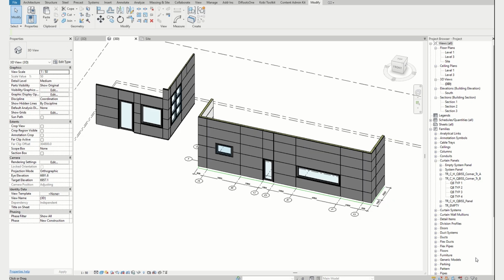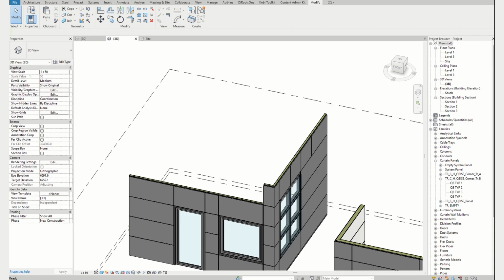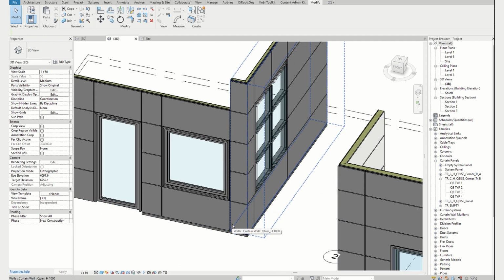We talked a bit about inserting doors and windows. What about the finishing details at the top and bottom? Our main focus were panels and corner elements, but of course we need to define fixing, flashings and ceiling material in order to build facade properly. All these materials are defined in Trimo typical details which are available on our website.